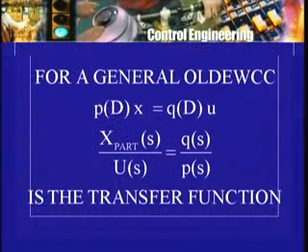You can think of applying the Laplace transformation and almost see that, okay, if I have d square x rather on the left hand side, I will have s squared x of s plus some stuff, so that d is replaced by s, but that multiplies x of s, and therefore it will appear in the denominator when I write the transfer function. Whereas if there is a derivative of u, there will be a corresponding s thing, but that is on the right hand side, therefore when I write it as x divided by u, it will be in the numerator.